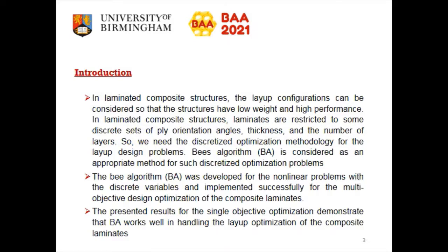In fact, laminates are restricted to some discrete sets of ply orientation angles, thickness, and number of layers. So we need to describe optimization methodology for the layout design problems. We successfully developed the Bees algorithm as an appropriate method for such a discretized nonlinear optimization problem in this research.